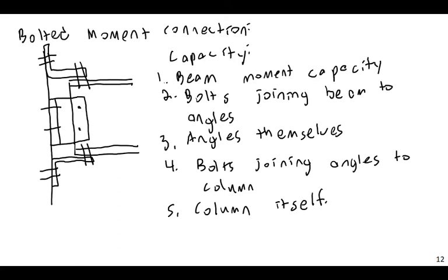So the downside of this is that there is no easy way out. There is no easy way where you can just say, oh, where's the equation, plug and chug, throw it in the calculator, and here's my moment capacity of a connection. You cannot do that when you're doing steel connection design. This is one area where you simply can't do that. Instead, you need to go back to your beam theory and say, okay, here's a distance, here is an area, here's the capacity. All of this is designed from very fundamental base principles, base mechanics and materials.